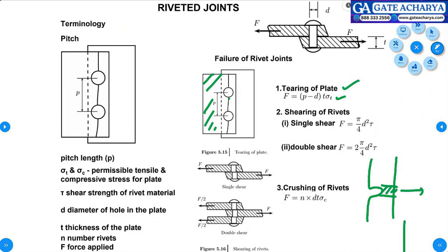Right. So I hope you're clear with when to adopt static failure theories and when to adopt fatigue theories. Right? When will you adopt fatigue theory? Anyone come out? When the load is cyclic. Okay, sigma applied is itself plus and minus. Tensile stress, compressive stress. Tensile stress, compressive stress. Okay, at that time you need to use fatigue loading.